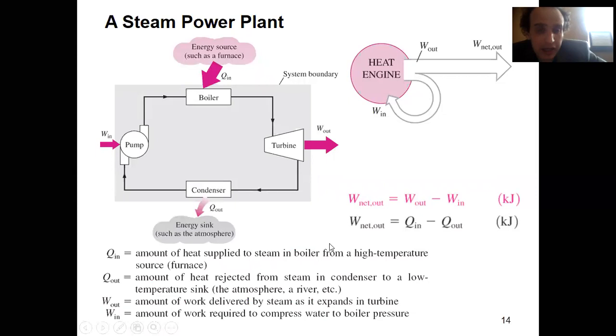So basically, typically, we may have a boiler. What we actually have here, we convert heat which comes in. Let's say you have a furnace, you have some kind of steam machine, you have a boiler, and this heat goes in. And you convert this heat into work. So how does it work? Let's say here I have a boiler. In my furnace, I boil my working fluid and I create steam. When I boil it, what does it mean? That I increase its enthalpy. My enthalpy is high now, right?